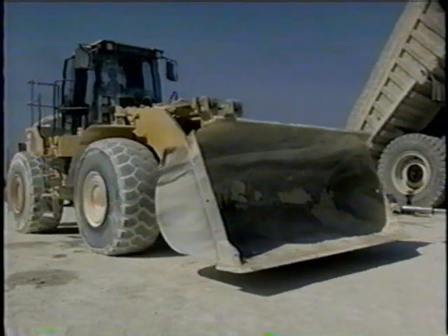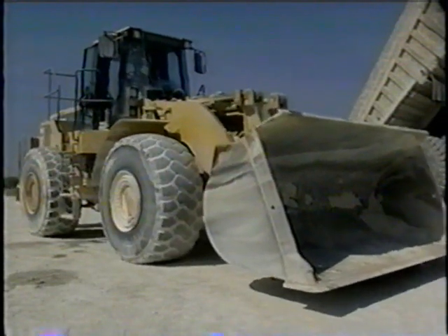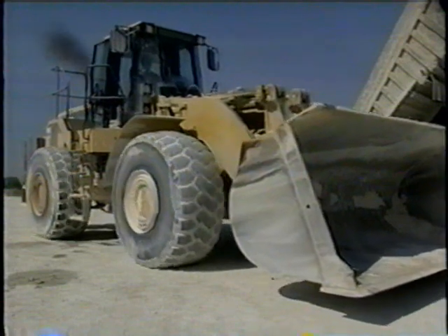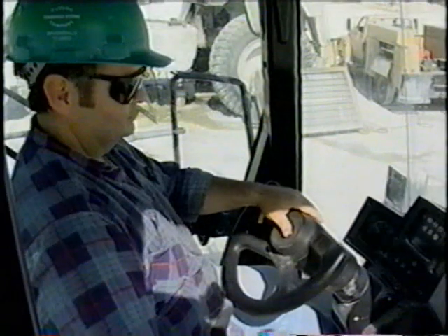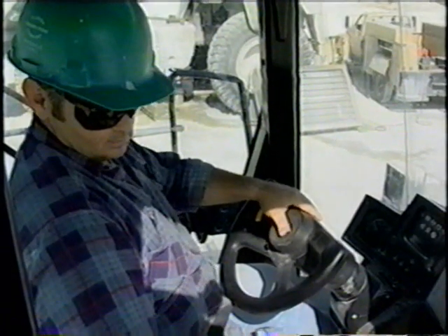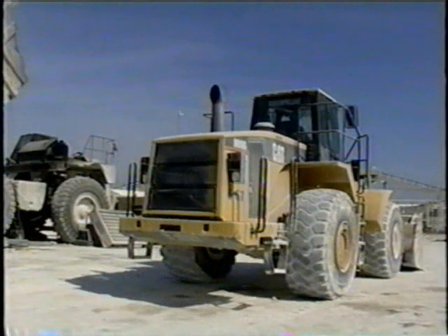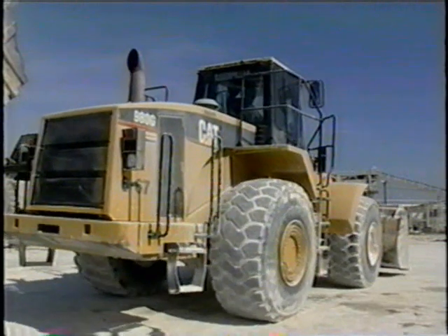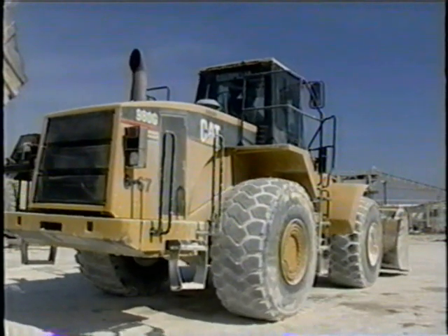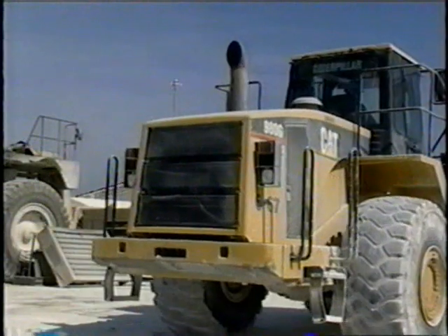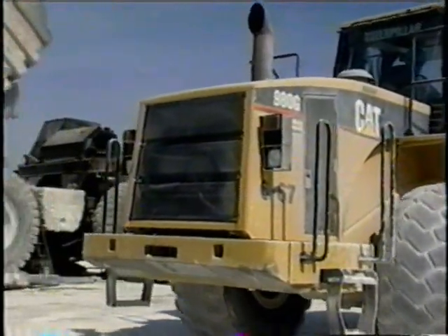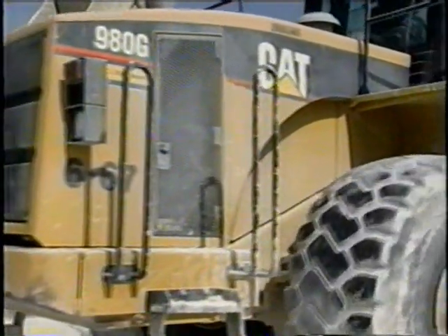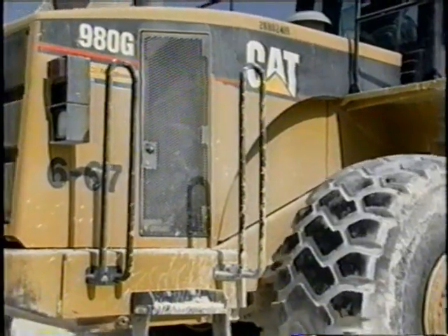The following general items are to be included. Brakes, both service and parking, shall be capable of stopping and holding the equipment with its typical load on the maximum grade it travels. Warning horns, including forward horns, backup alarms, and travel alarms shall be functioning with a decibel level high enough to be heard in the surrounding work environment. All equipment with an obstructed view to the rear, including service vehicles, shall be equipped with a backup alarm.